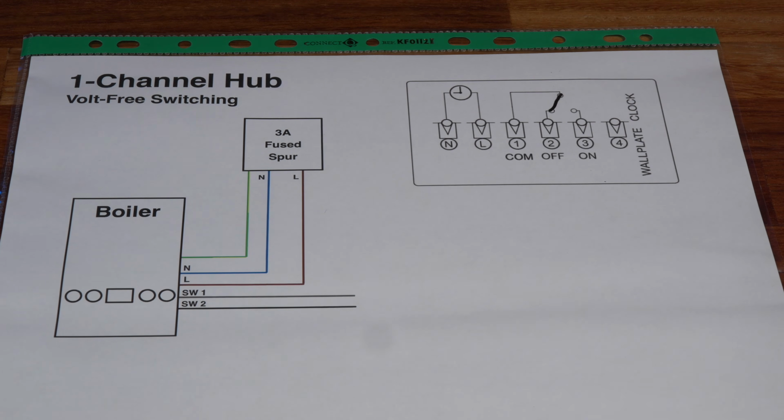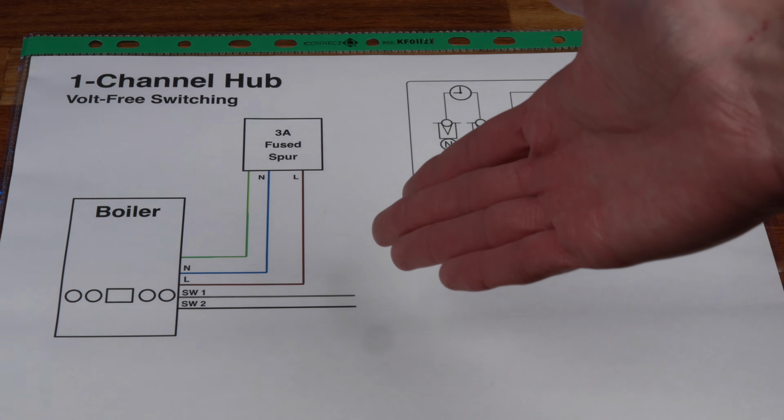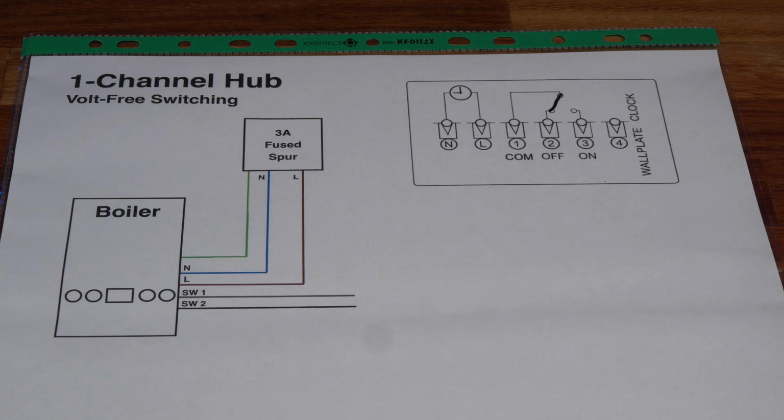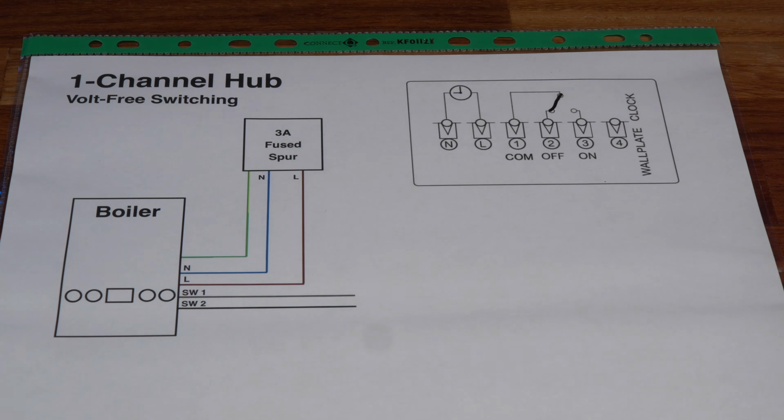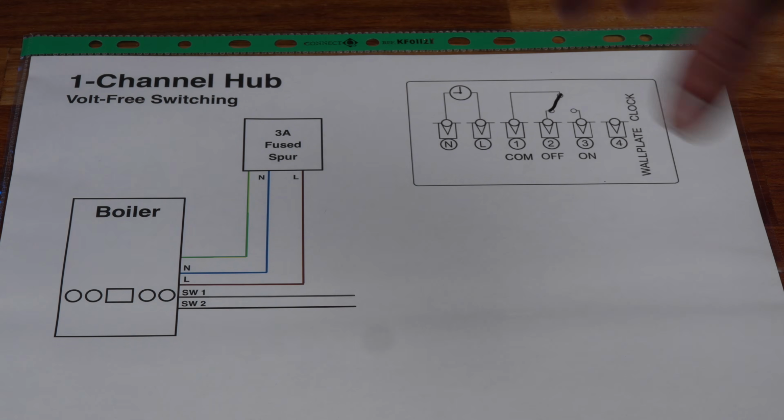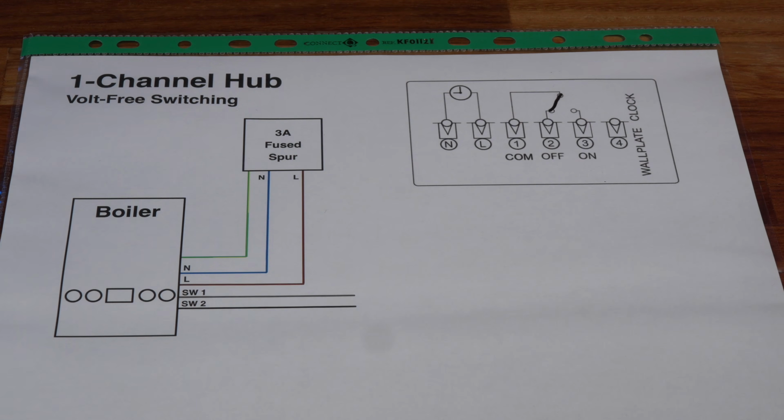Now, of course, with your particular setup, these wires aren't going to be neatly hanging outside your boiler. They're going to be connected to your existing thermostat. So if you have an existing wireless thermostat, all these connections will be wired into the existing wireless thermostat receiver that will be installed somewhere near your boiler, and you just need to replace that with the Wiser hub. If, on the other hand, your thermostat is located somewhere else, and then that's wired back to the boiler, you need to find out where these are connected and reroute all the wires into the Wiser hub. A good place to look for this would be in the back of the fuse spur, because likelihood is that they're all connected through in there. You'll be able to disconnect that and wire that into your Wiser hub.